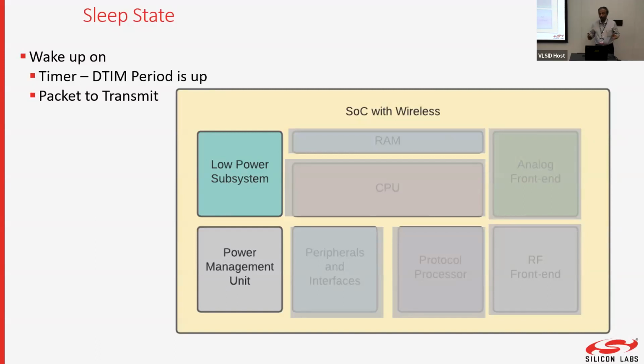Everything has to be intact. You don't want to redo all the security handshakes because that will take up energy. And if you want to store all of that, you can have RAM retention logic. RAM retention allows you to store data in RAM at a small cost, a few tens of microamps for sure, but it can store it. And when you wake up, it will save you a certain amount of time.